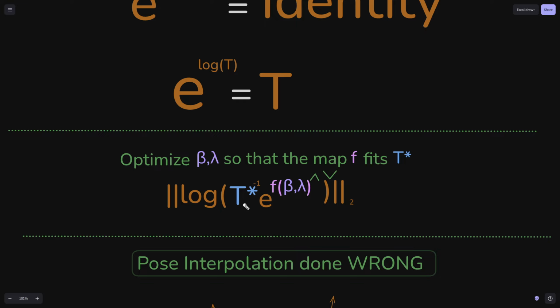For the practical case, you might weight it because you might be more interested in the angular error or the translation error. And sometimes translation errors will be very large in kilometers, and if you measure them in meters, will be very large, and basically you will ignore the angle. So most of the time you will weight it. In small robots like the UR5, the Universal Robot, you may not weight it, and you may apply this directly, okay? Otherwise, you would weight it.